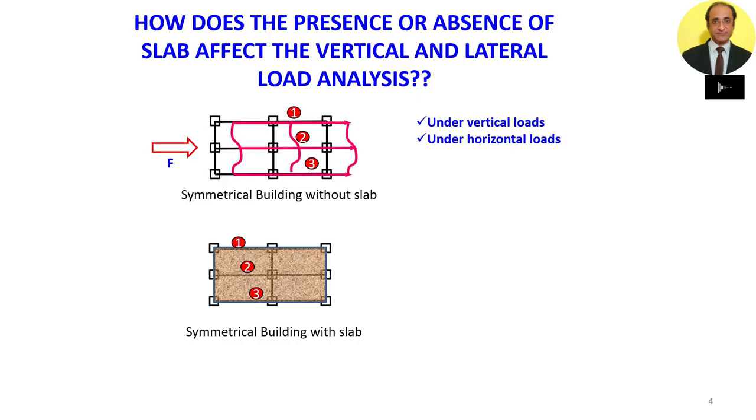What we can observe is that frame number 2 is undergoing larger deflection because the force is concentrated at frame number 2 only. We can also observe that the beams have undergone lateral bending. So here the compatibility is a bit different. Axial forces will be generated in the beams and there will be lateral bending of the beam. So it is like a non-uniform distribution of the lateral loads.